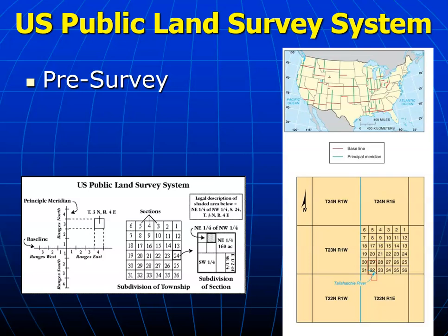So you'd send surveyors out there and they would mark off highly accurately a couple of lines. You'd have a very accurate baseline, what's referred to as one running east-west, and then a principal meridian, one running north and south. And you'd have 1 mile and 6 mile increments indicated on there, and they would have a code that they would use. And then they would go back and resurvey other areas with a much quicker method, literally taking chains of a certain length where they would flip over and measure off distances very, very quickly. As long as they could correct those every so often with the highly accurately surveyed locations, you ended up with a pretty good grid system.